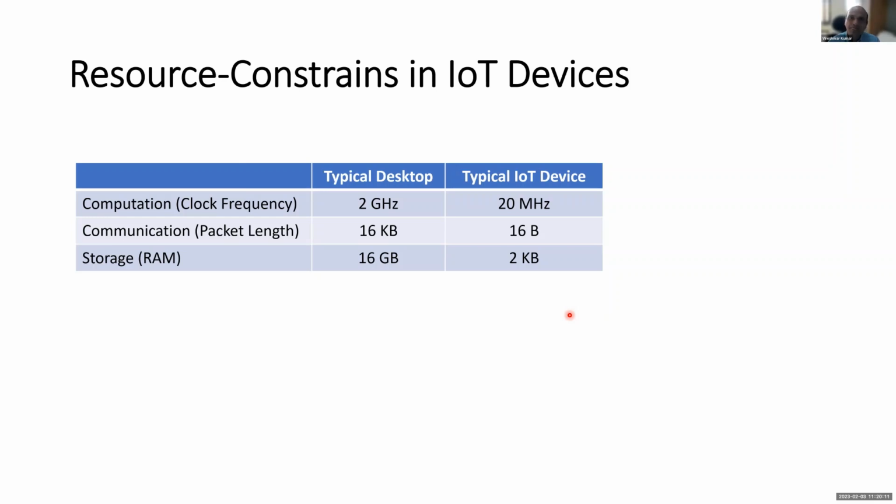Therefore, in a typical IoT device setting, for let's say a smart ring or smart watch, the design that is preferred is that we use communication protocols which are lesser in bandwidth, which require lesser packet sizes, and which ultimately results in spending lesser energy from the device side.